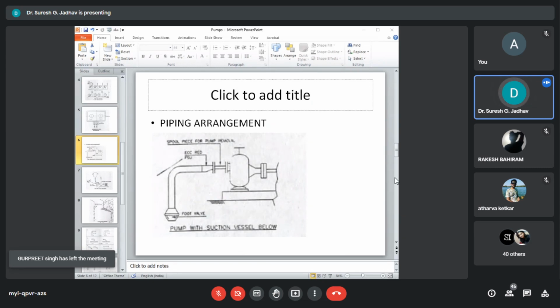The nominal size of the header has to be checked while locating the pumps and routing the suction lines. Accordingly, saturated liquid, steam condensate, and vacuum conditions need elevated suction vessels. The horizontal run should be kept minimum in all suction pipes.